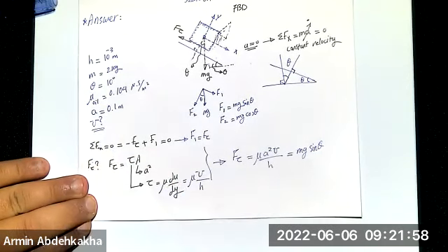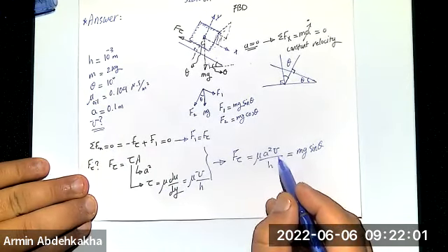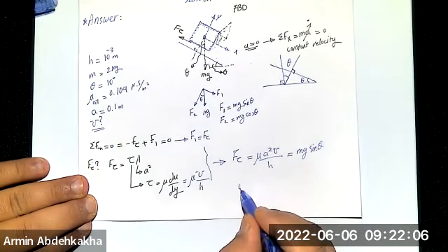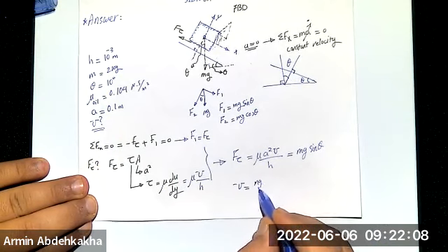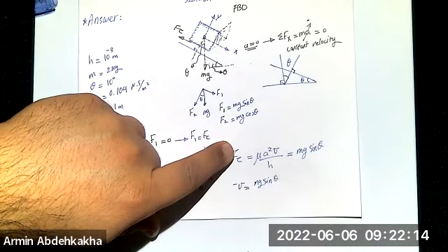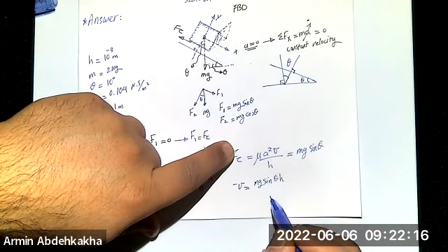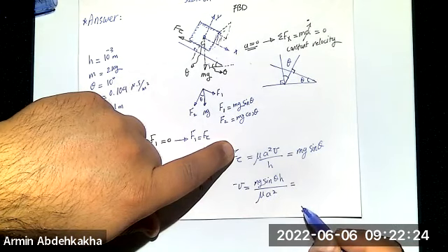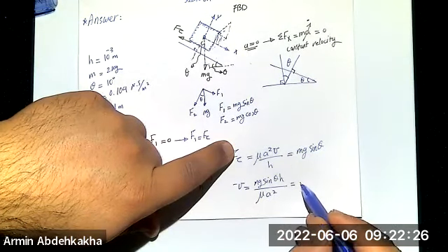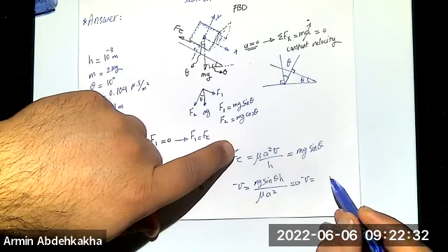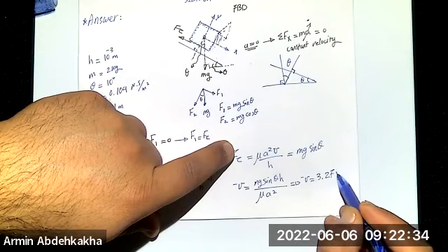U. Keep U on one side and the rest of the known parameters and terms on the other side. So U is equal to mg sine theta times H over mu A squared. If you plug in the terms, then the final answer U is 3.27 meter per second.